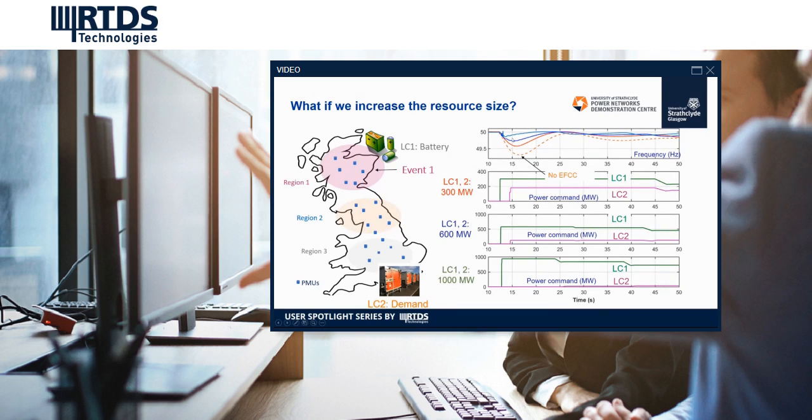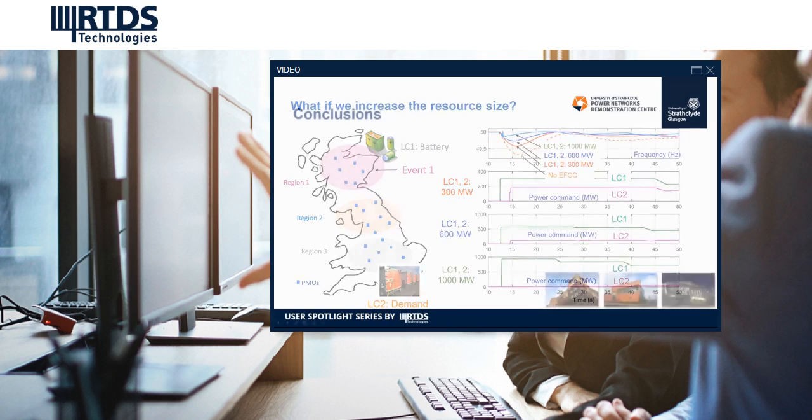If you see, in this case, without any EFCC, the frequency can drop to 49.3. And if we have a lot of faster response, we will be able to control that within a very small deviation range. And that demonstrates the value of a faster frequency response in the future system to support the frequency regulation.